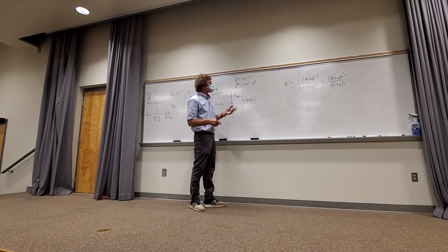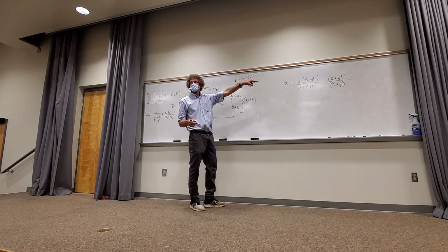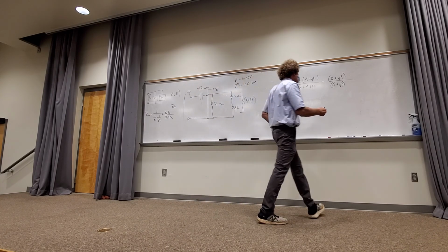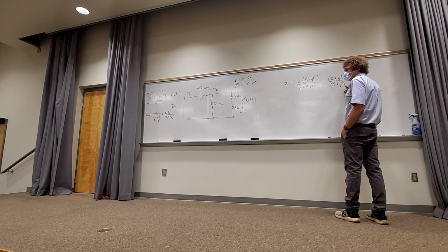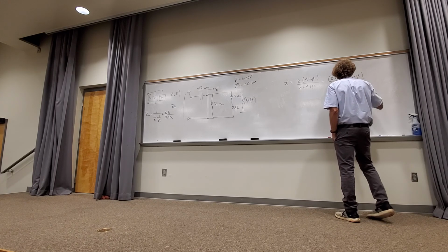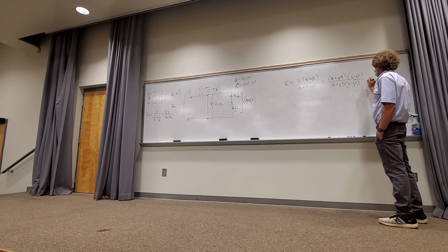Conjugation also means if it is not magnitude and angle, you simply flip the sign on the imaginary part when you take the conjugate. So a complex conjugate multiplication starts down here, and you simply multiply top and bottom by the conjugate of the bottom. It's called the complex conjugate of the bottom. You with me, class? Now the reason I do this is I get a strict rule here.